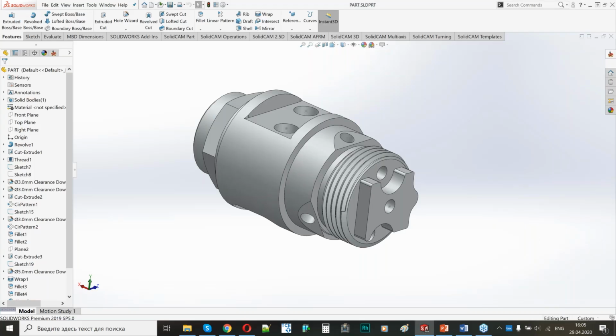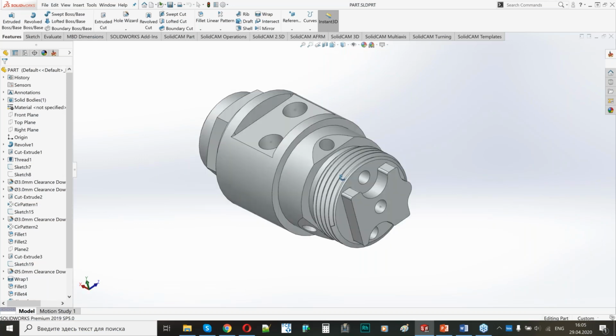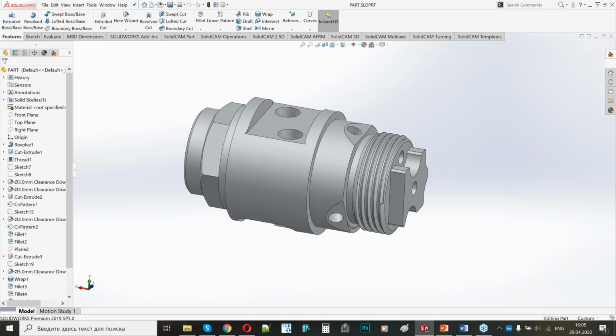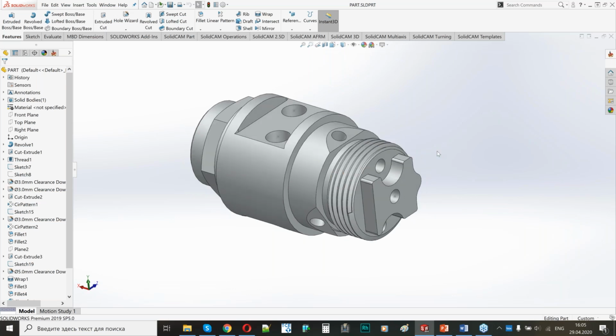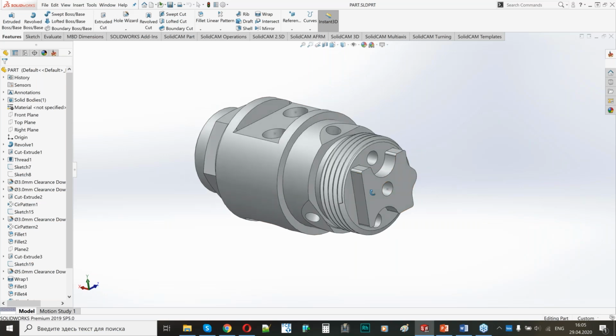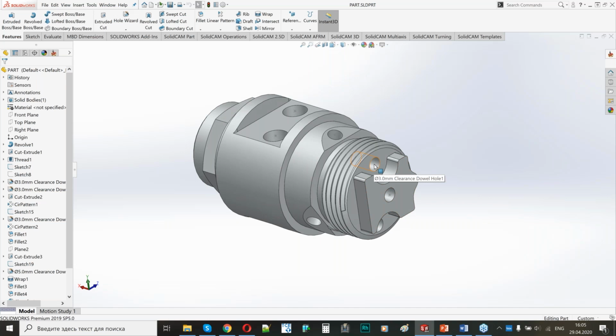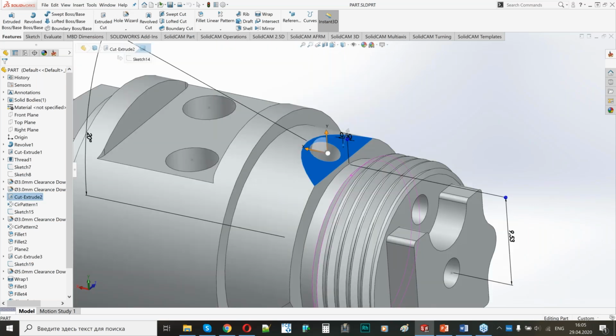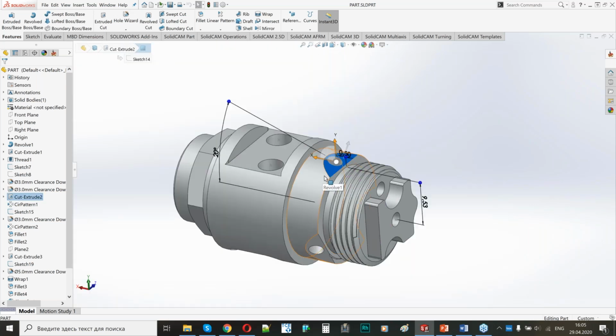It's like a standard solid CAM part. Maybe you seen it previously in our sessions. It is very nice to show different examples of programming, because this part has both drilling, turn drill, some drills on a face, on a radial direction, and inclined elements. We're gonna use B-axis today.